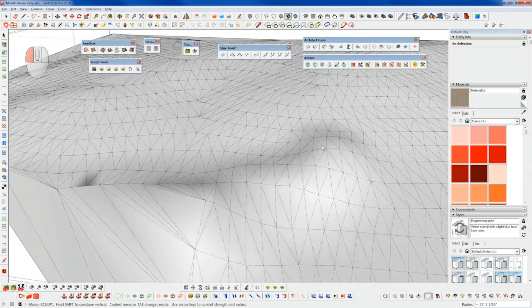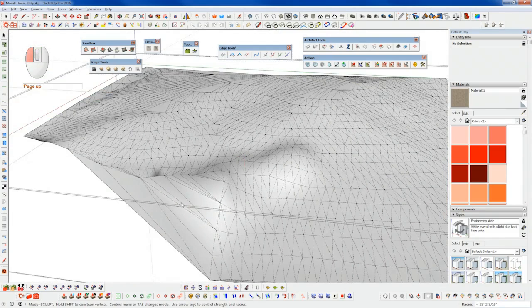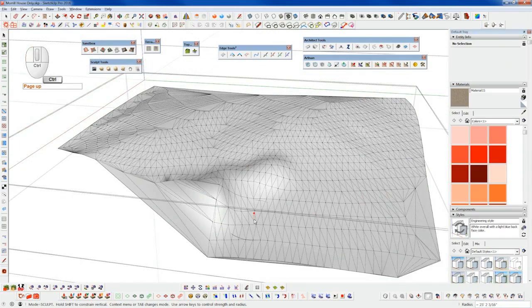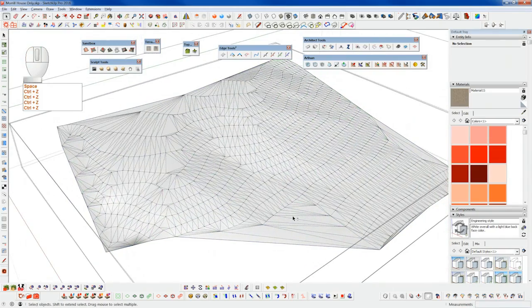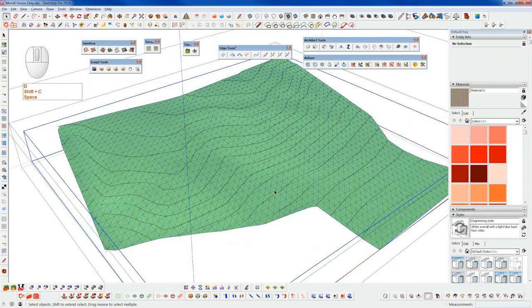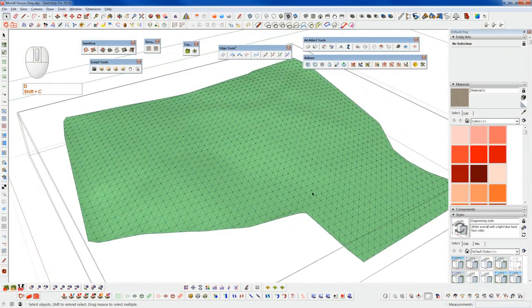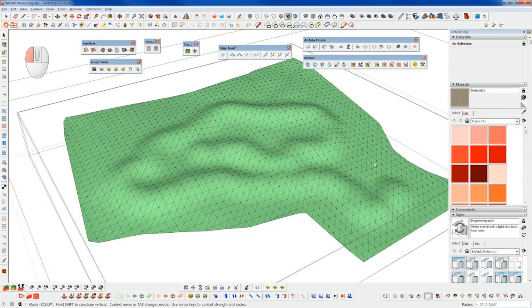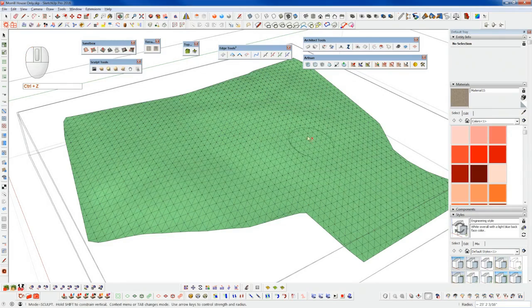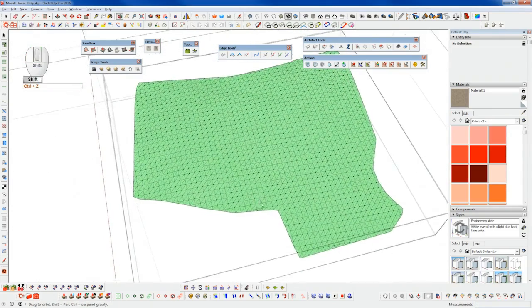They don't want to sculpt at all. Over here, we'll get a much better sculpt, and as soon as we get over here, we can't sculpt because we don't have the subdivisions to allow us to sculpt. So normally we'd have to go in and delete those edges anyway, but the difference here with our mesh from Topo Shaper is we can sculpt that, and we have a very nice clean sculpt anywhere we want to sculpt.